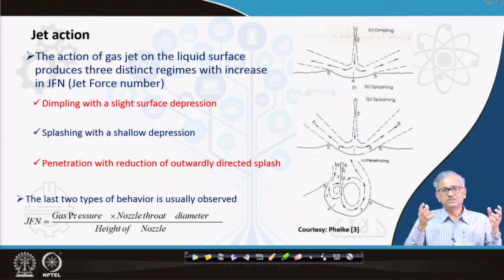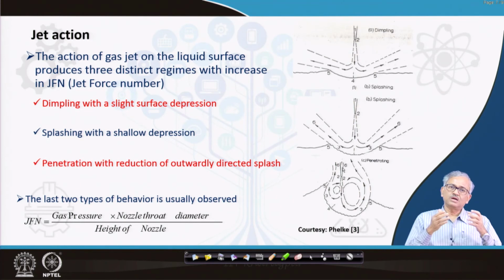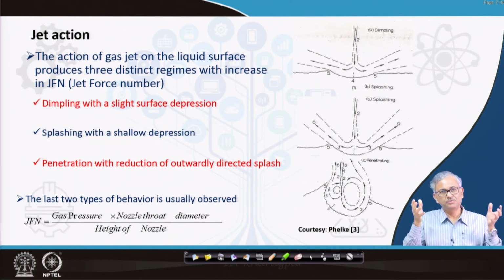a large amount of impurity like phosphorus in the liquid iron, a large amount of phosphorus. So what you have to do is continue with the carbon to the end of refining. In that case, initially you do some soft blowing such that you build up the FeO, because the FeO buildup is very important for the CaO dissolution, calcium oxide dissolution. Also, calcium oxide does not dissolve immediately, some temperature is required. So after some time, when the temperature is high and FeO is significant, CaO easily dissolves, makes the basic slag, and then the dephosphorization starts.